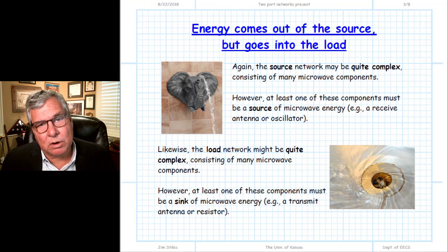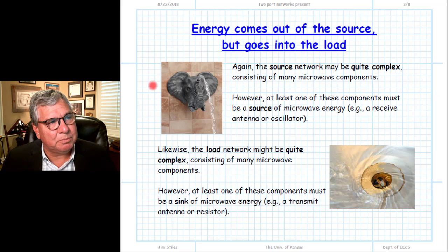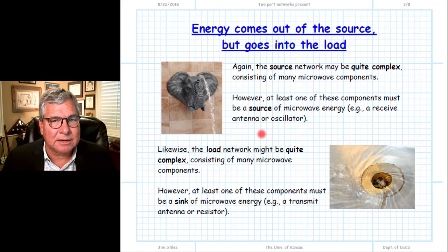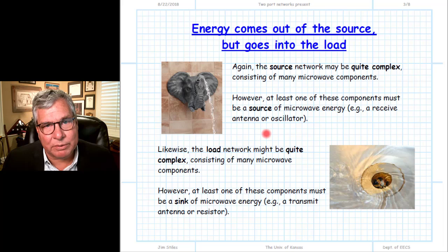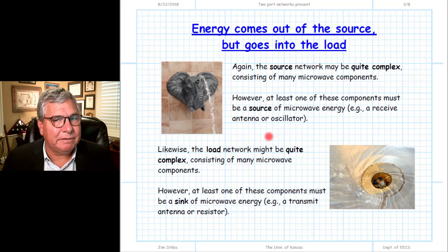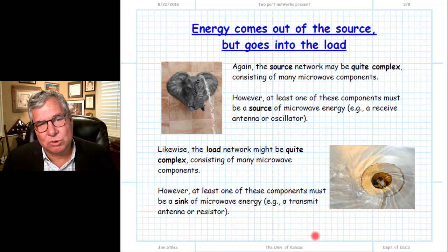So as we've talked about before, everything to the left of the input of that two-port device, we're going to group in something called the source, and the source is just the device from which energy is flowing at a certain rate, and so we call it the source power, or specifically we are concerned with the power delivered by that source. Everything connected to the output of our two-port device, again, we're going to group into an equivalent circuit, which is the input impedance, and that is the load, and that will absorb energy. And so there's a rate of energy flow that we call the absorbed power, the power that's coming out of the two-port device and therefore being absorbed by the load that its output is connected to.